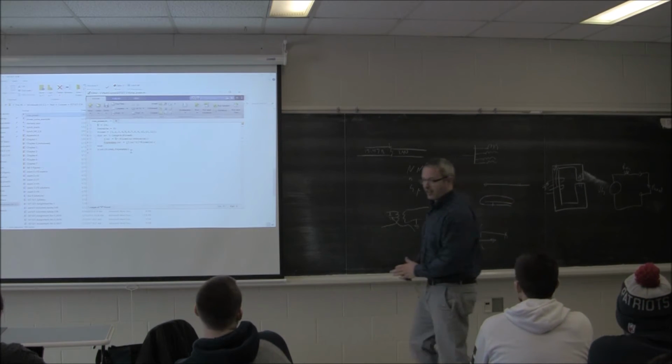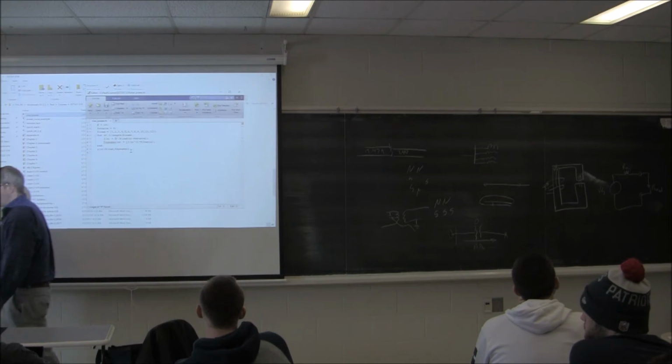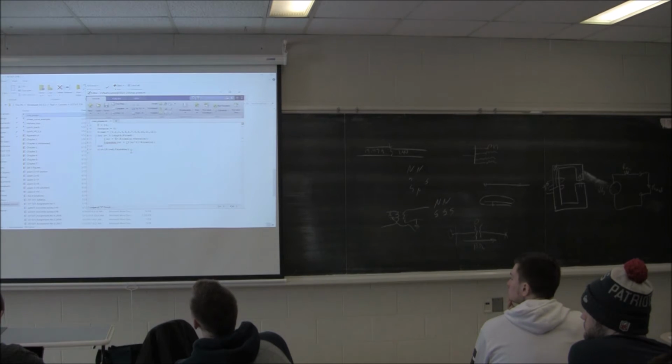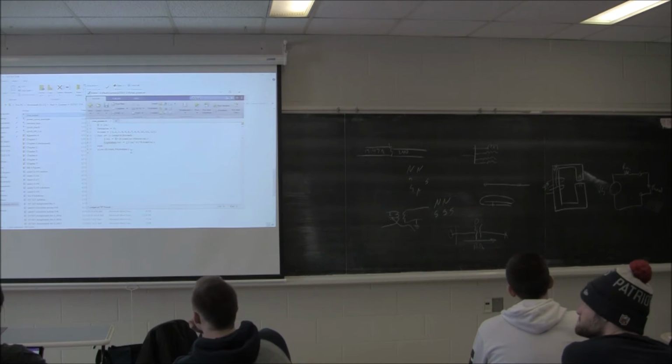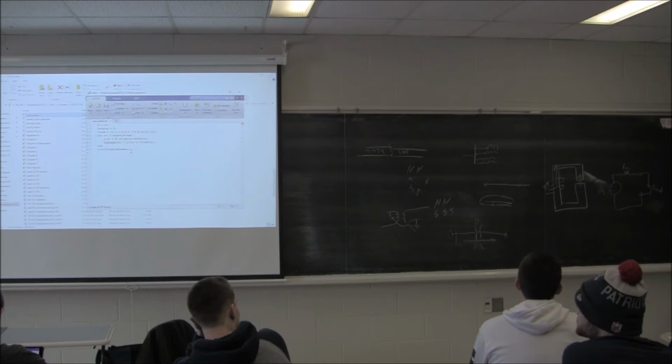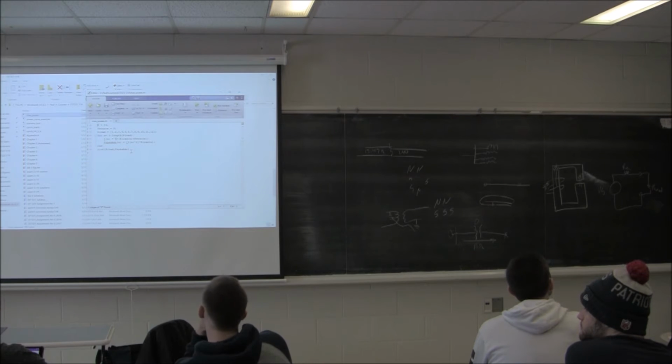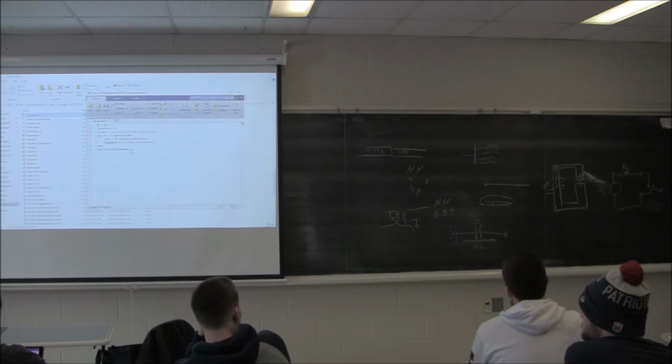Does anybody here use the, I know they used to do this for Agilents, but we have the Reguls. I don't know what ECE does. But do you ever have to go into your AC function generators and adjust your source impedance? No? Sometimes you enter in a voltage and your source impedance and it doesn't match what you specified, and the reason is because it's trying to predict what the voltage needs to be internally to give you a desired voltage on the output. They know exactly what their source impedance is, and they're trying to predict based on your load. So oftentimes with a function generator, you have to go in and say an infinite load impedance. So basically this voltage here is going to be the same on the terminals regardless of the load, as long as the load is small enough.